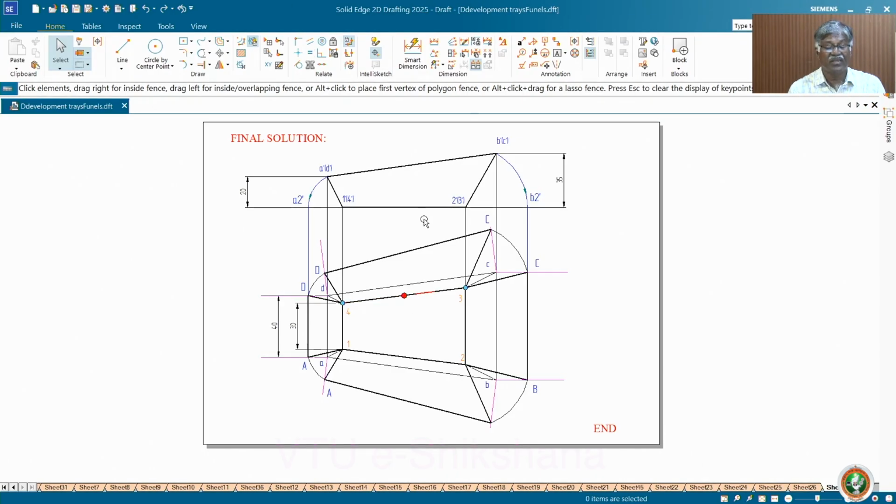You will get the top and front views, particularly for trays. The dimensions, you must post as per the given values and see whether it is different height or same height carefully, and then work out. So again, I repeat, I conclude, whenever you draw a locus through the moving end or the outer corners, you must see that it is perpendicular. If it is rectangle type, two mutually perpendicular lines will work from each corner. If it is inclined like this, then you must be very careful. Draw perpendicular to the base edges.